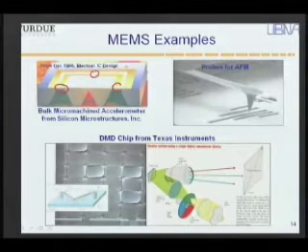This example right here is the DMD, digital micromirror display chip from TI, that's now found in most commercial projectors. It is composed of a chip here, where the chip actually has lots of these metal mirrors, where each mirror can be deflected along an axis, and it can send light towards the lens or off the lens, and hence projected. So essentially your image is now being sent digitally to the chip, and each little mirror is addressed to turn the pixel on and off.